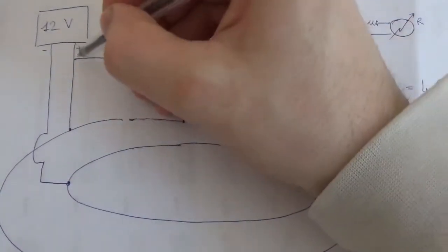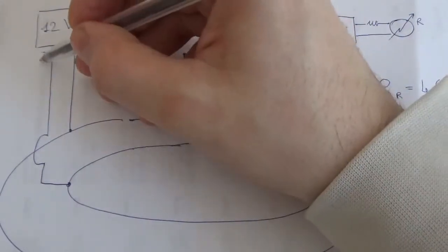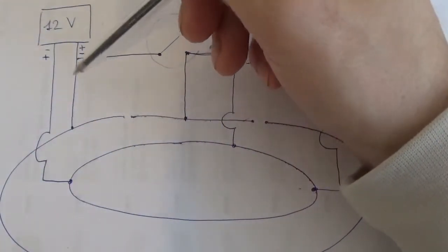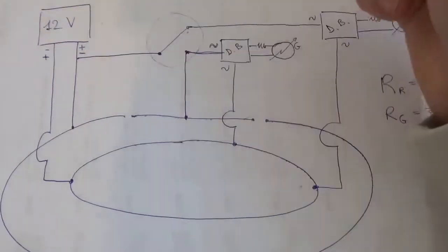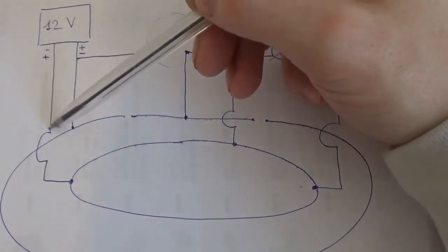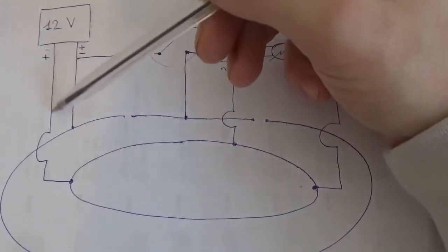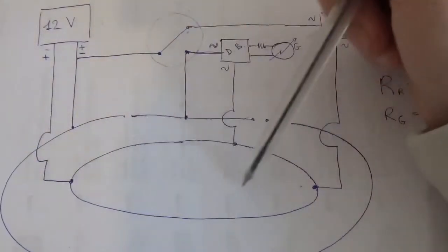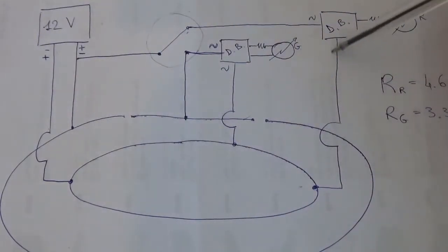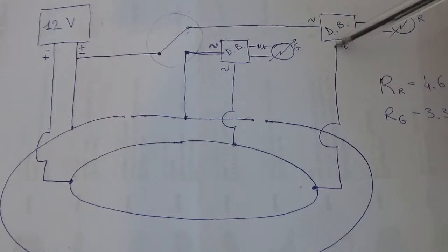But let's check how things work with the opposite polarity. Okay, so in this case with plus here and minus here, the electric current flows in this direction, powers up this part of the rails, goes all its way through the diode bridge from this input here.